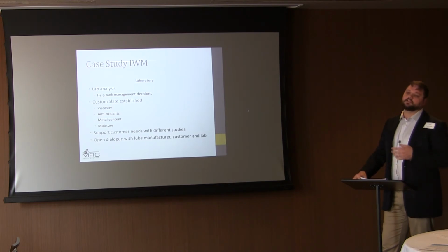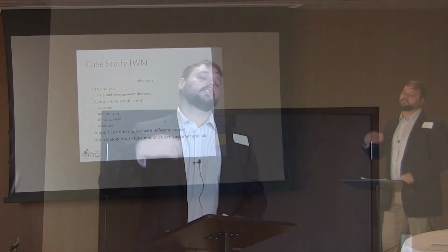So our job as the lab providing feedback is helping the company make tank management decisions. So if they're seeing that the viscosity is going up really high and that the phosphate and ester levels are dropping, they're going to add some more fresh oil. It's going to increase their levels and decrease their viscosity. So it's kind of a cat and mouse game: you see something, you take action to prevent it from becoming a problem further down the road.